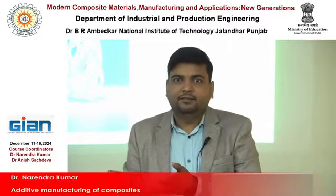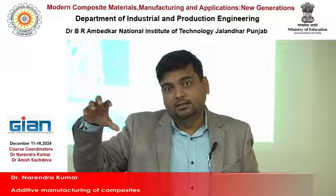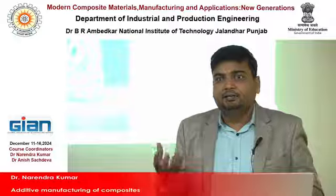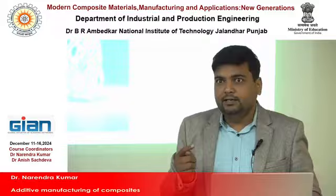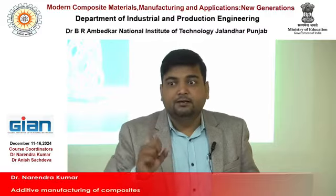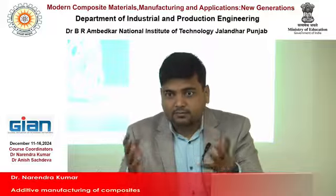If you ask, sir, can we make this? We have to assess the features of the 3D printing machine that is available with you. Only then can we say that this complexity can be achieved with the available machine. Otherwise, we cannot claim that any complexity can be achieved by FDM, SLS, or SLA printers. So whenever you are planning to make a complex object, first of all, you need to check the machine. What machine do you have? And you assess all the features and specifications of the machine.